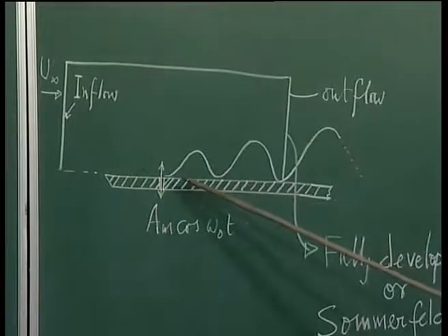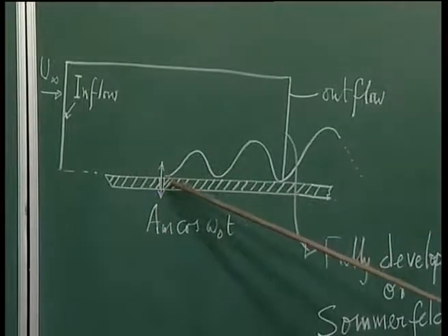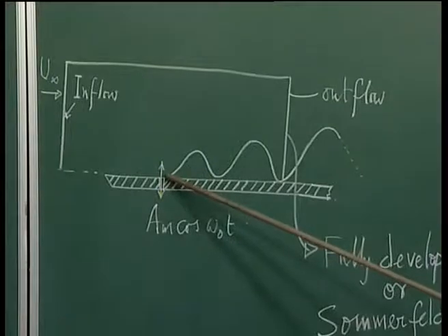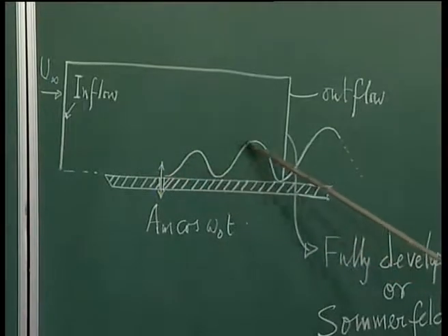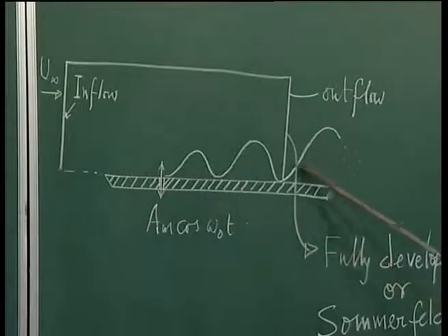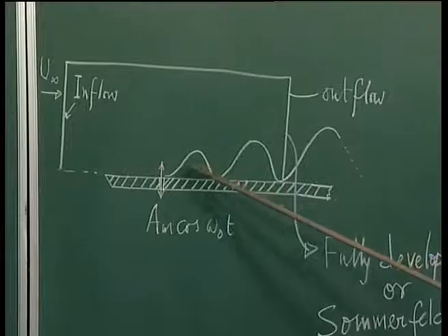And what happens during the evolution of the flow is nothing but the growth of periodic disturbances that actually grow in space. Now, if you excite the flow here, these are essentially unstable waves, physically unstable waves. That means the amplitude keeps growing as you go downstream.